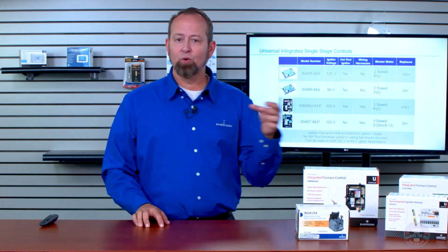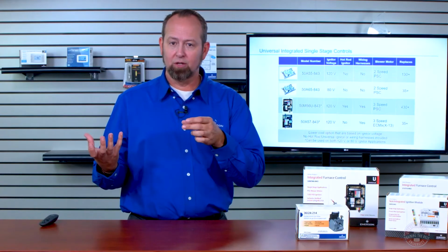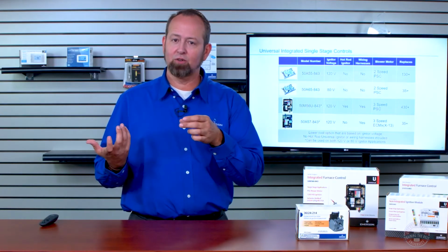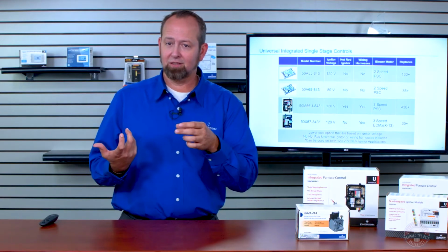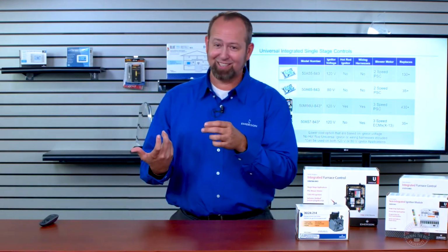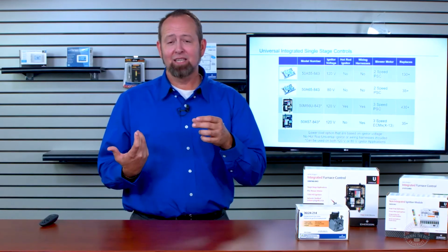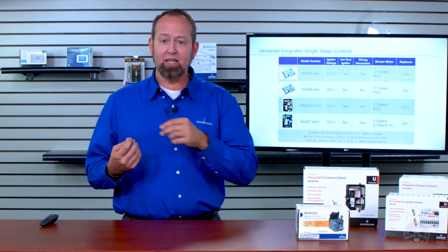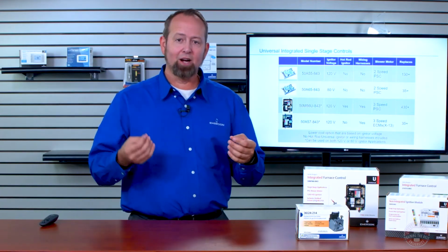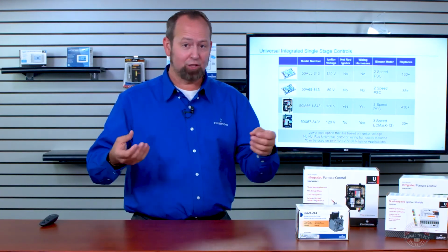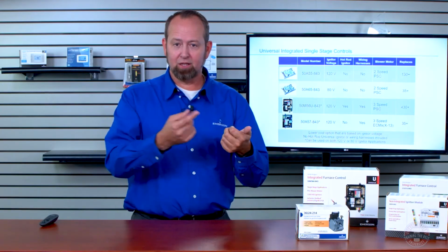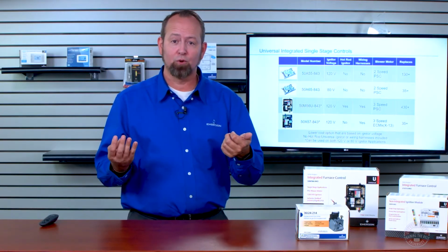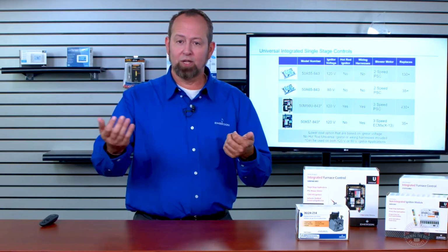You have line voltage going into that motor. Now that motor does have a module that's going to convert that line voltage to three-phase, which can kind of be a separate discussion, but that is voltage going in, and then you have low voltage, which are different wire taps that are 24 volts, just like the 24 volts going to a contactor. There's a common 24 volt, and then there's 3 or 4 different 24 volt speeds that determine which blower speed you have.